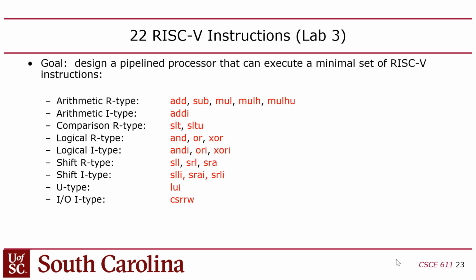But we're going to take advantage of the fact that the program counter will increment from 0 to 4191, and then roll back to 0. So we'll get kind of a free loop in here. The code will loop on itself over and over again, right? As long as we just need one infinite loop and no decision instructions, then we should be good, right?